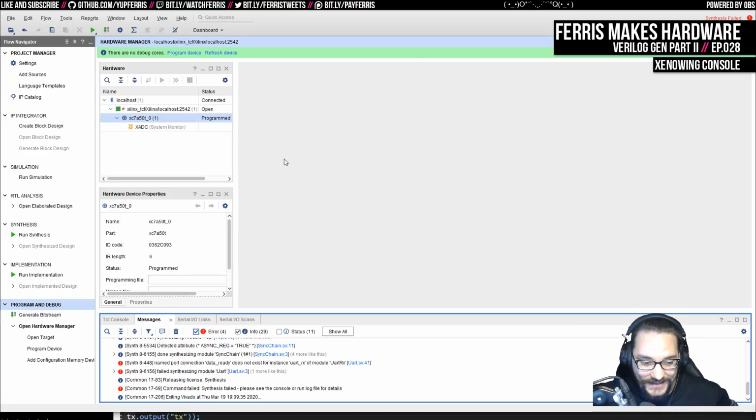So I guess I'll show this flow a bit more later. But the point is it's that easy to set up, and I just totally missed it. And this was really valuable in debugging this because I could clearly see that after synthesis of the design, again, that register was gone, and then I could also look at the other signals. And I could see that all the timing looked good because just like we did in simulation last week, I was able to tap into different signals like the states that we looked at and saw that they looked exactly the same on the hardware, so it couldn't be that. And then eventually I was able to narrow it down to that codegen bug, which is great.